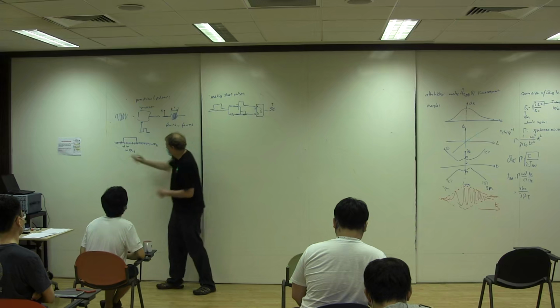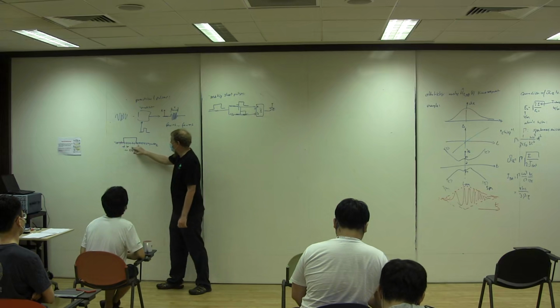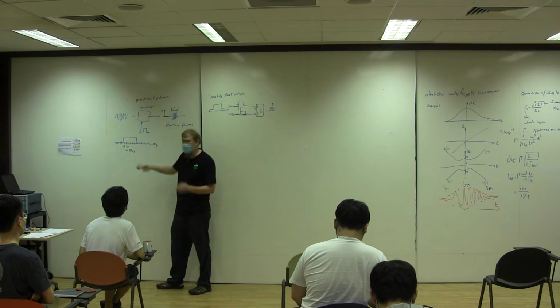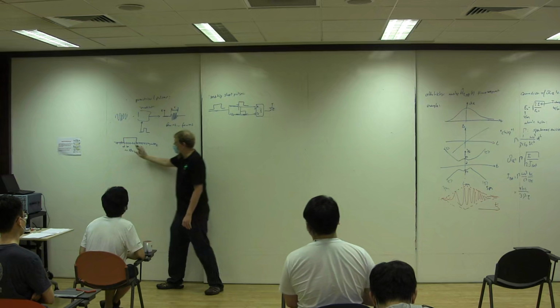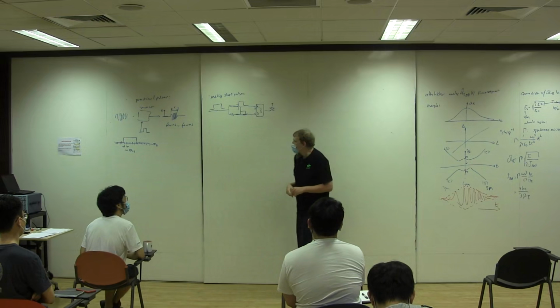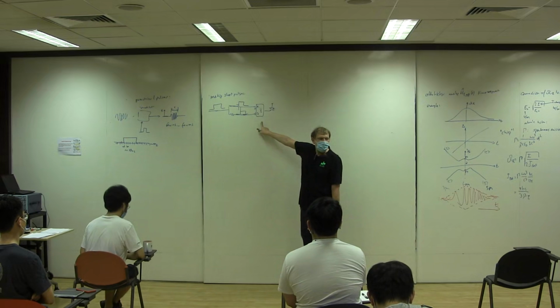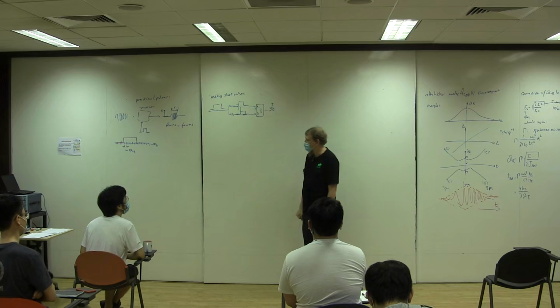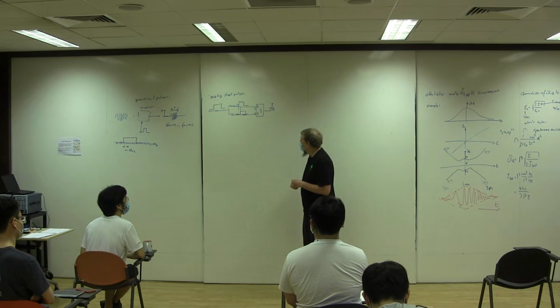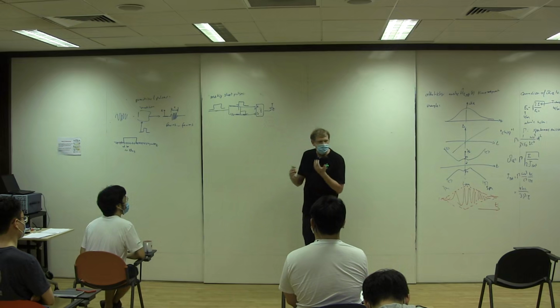Okay, say you have input lines that correspond to these pulses, and then you serialize the input of these 16 lines, and then at the next time slot, you serialize the rest, and in this way you can get these things much faster. But this is a simpler technique, and we can just play with them with some cables. I'm not sure whether I set something up, so maybe you can see this in a short while if I get the screen working here. So that's a cheap and dirty way of making short pulses and adjustable pulses.